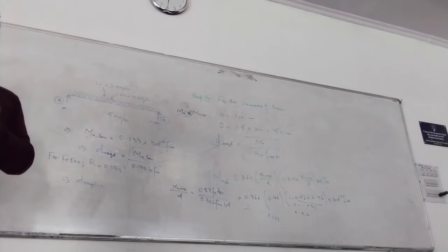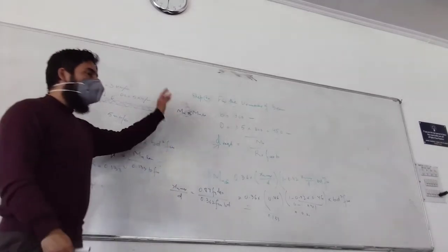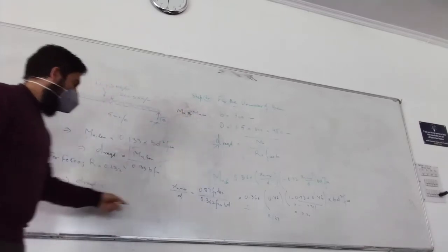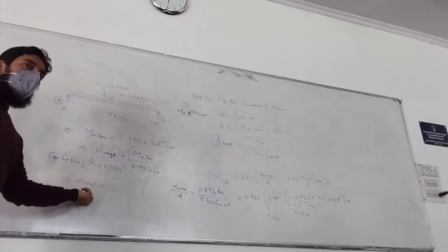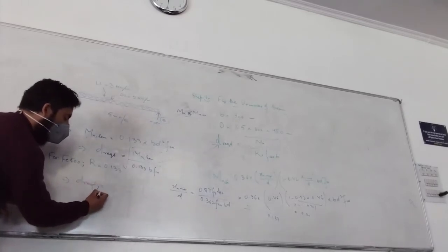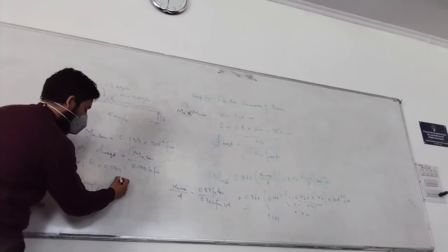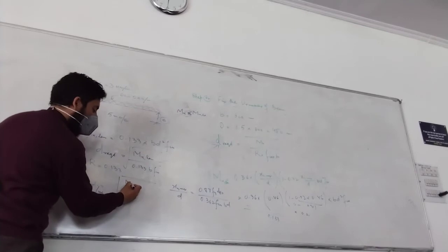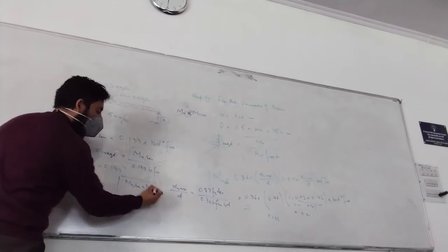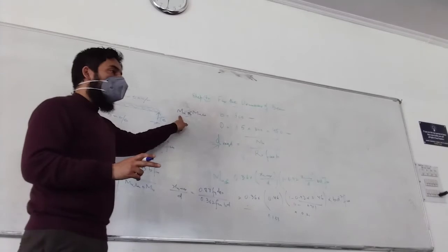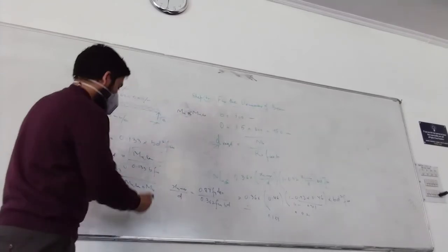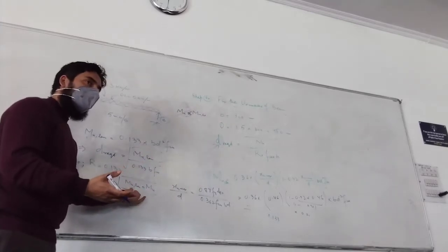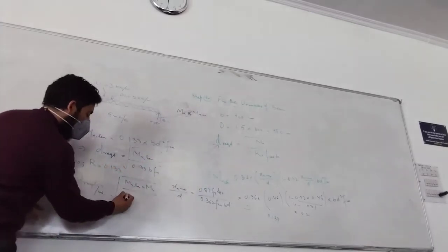So what is your concept? The design has to be under reinforced. I told you last time, if you go through that lecture again, mu should be less than mu limiting. So this then becomes D required, or you can say D minimum. How much is that now? If your mu limiting is equal to the mu that we gave as the load, I don't know what the mu limiting of the section is. If it's equal to mu, then you will get D minimum.